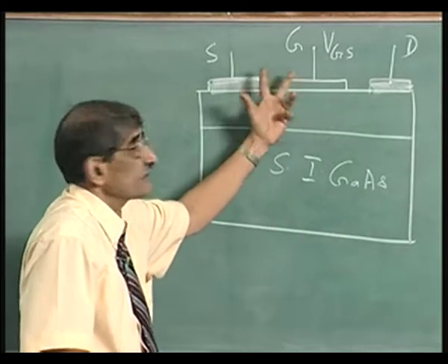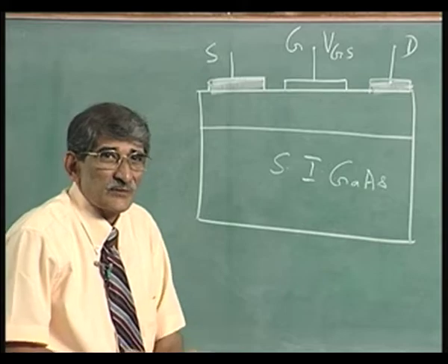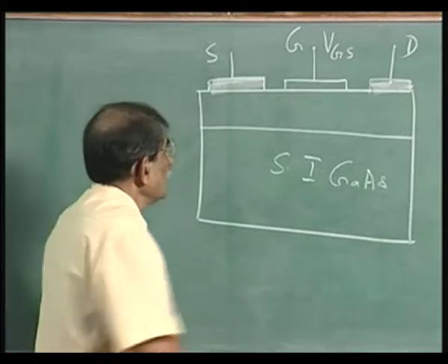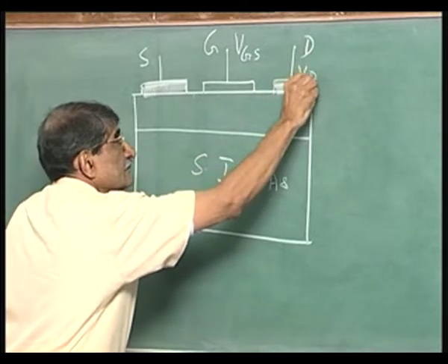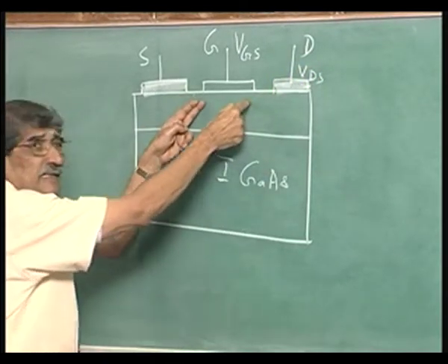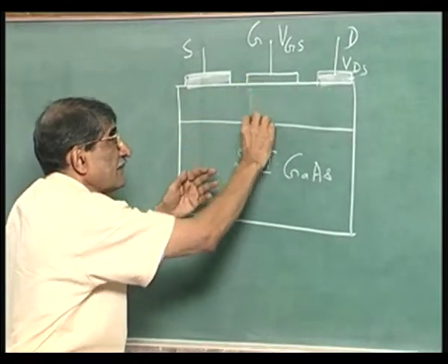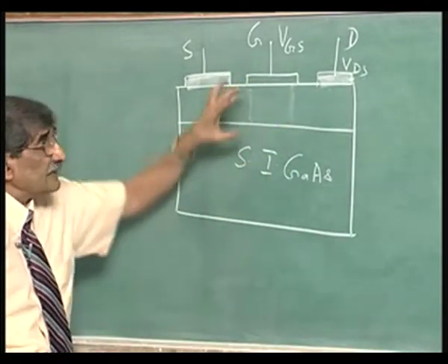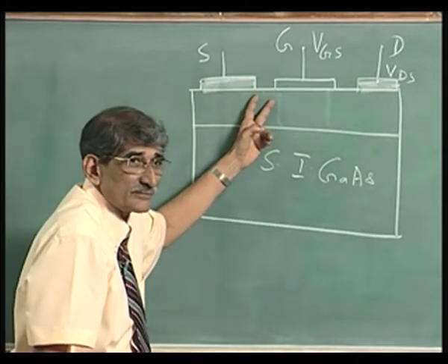Polarity is, you have to decide whether it is plus or minus. If it is plus, then it is forward bias. If it is minus, it is reverse bias. I am reiterating it so that there is no confusion about that VGS. So, here, the drop VDS we are taking across this, neglecting the drop here, because whatever happens is happening within this region. The gate has control only in this region, the gate does not have any control in this region.